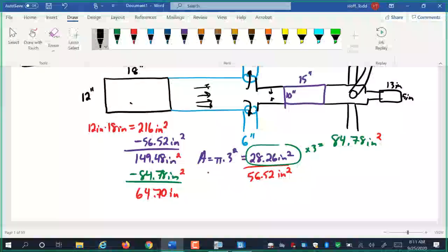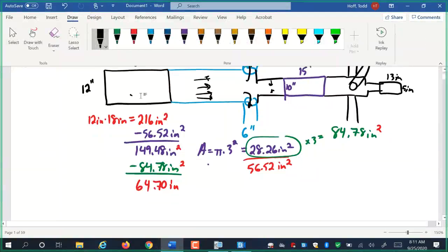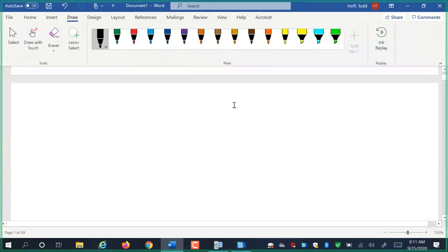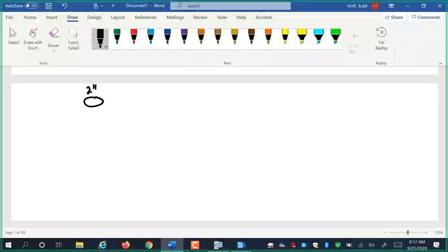The same concept applies in the other direction for water flow in a house drain. You have to prepare a house drain to handle full flow from all inlets. So let's say we have a 2-inch drain coming from a shower.